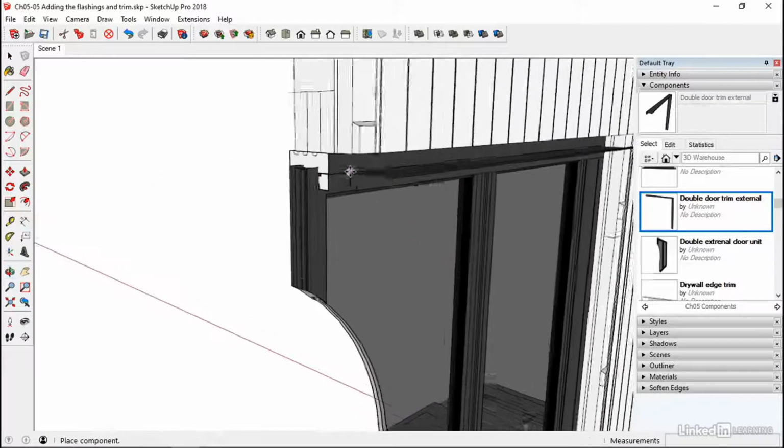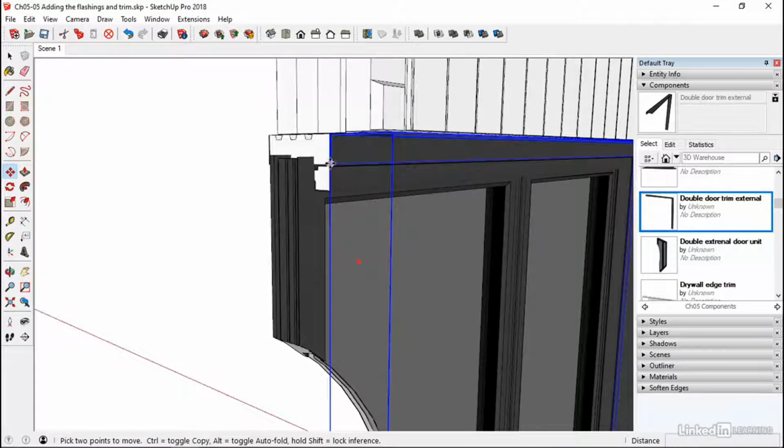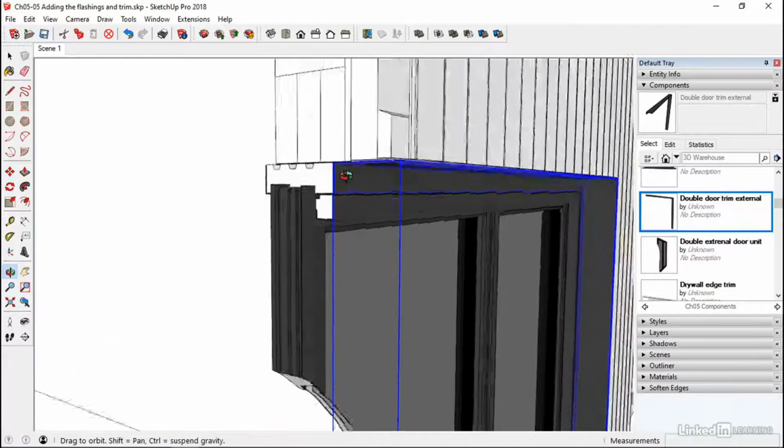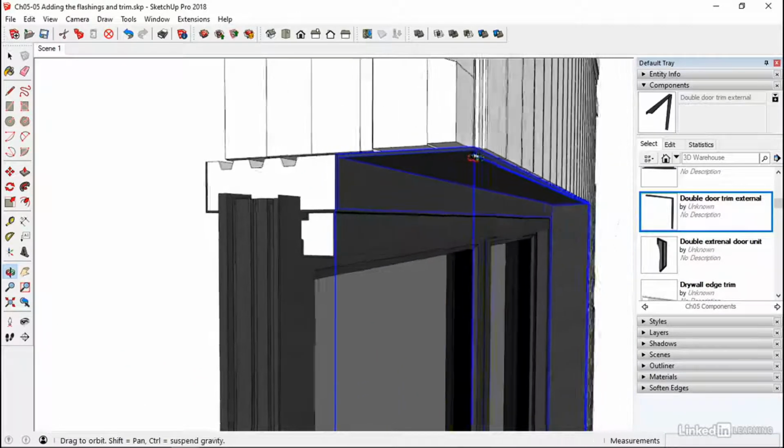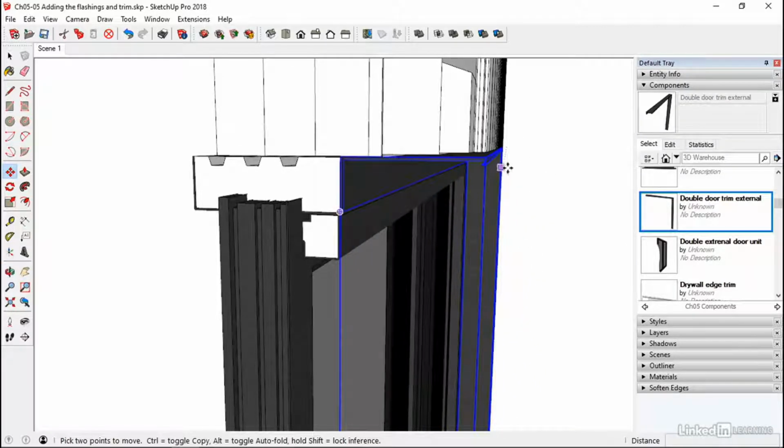This is going onto the subframe. Okay, so this will be fixed along. Whether we have this drop down as excessive as we have is going to be up to the design, but what's going to happen here is this is then going to shed water that's coming down this. It's also sloped slightly. We've got these capillary breaks as well.